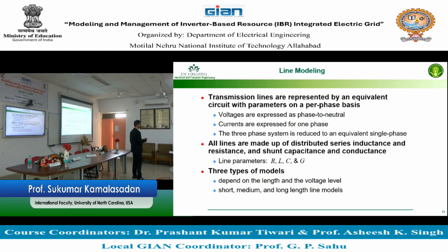You may ask, is the electric grid studied differently before? For power flow, we used to study the transmission network and the distribution network sparingly. Now, if you want to have the inverter based resources connected to the electric grid, you must study the power flow for the transmission and the distribution network together. That was the premise.